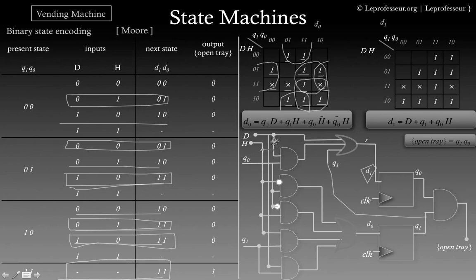Okay, and 3 input AND gates. If your technology library doesn't support 3 input AND gates, you can convert this 3 input OR gate into AND gates or other logic gates. This is here just to explain that we are using 3 input OR gate and AND gates.